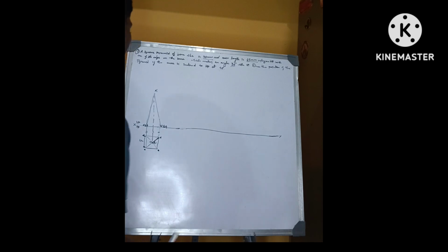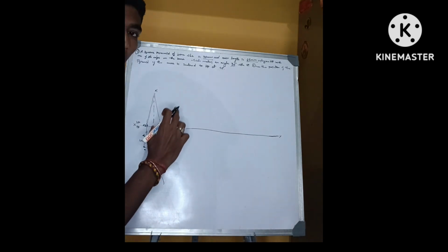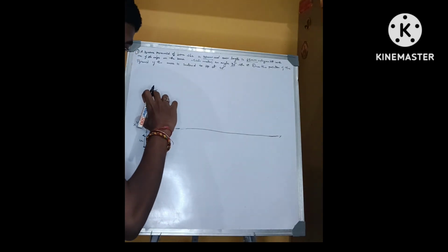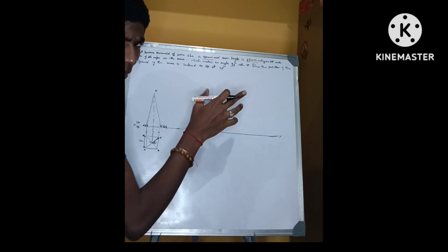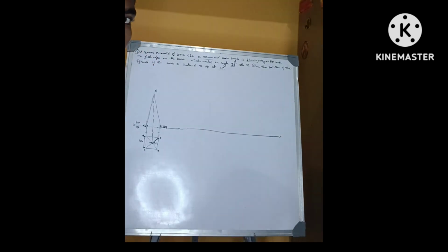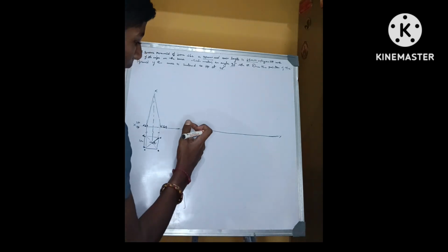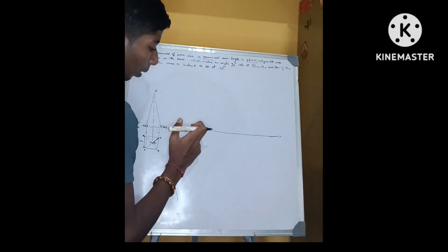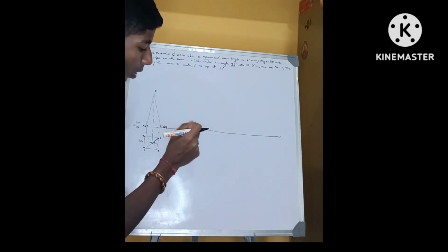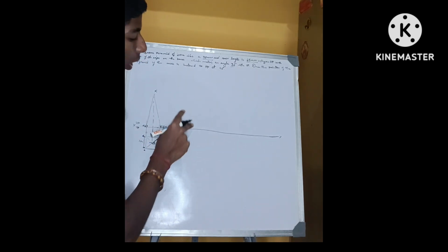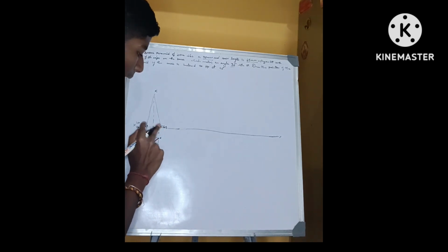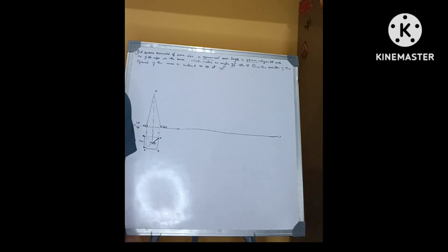Whether you call it a short trick or whatever, it can be an easy method for us. Now on the computer, you just copy this and move it and do the same things. But here manually you have to take a line of 50 degree from here. Take the protractor, keep it here and take 50 degree, and next take this as a radius and cut an arc. You will get AB. I hope you got my point.